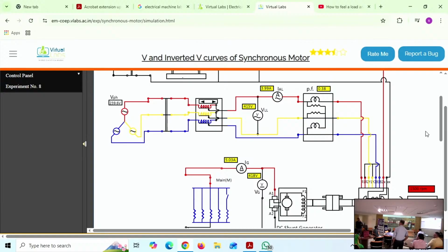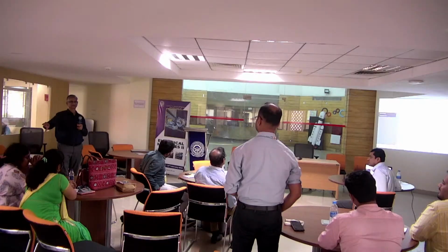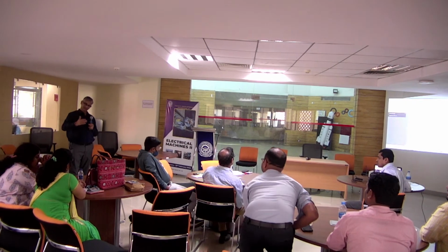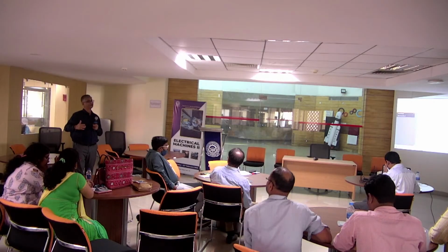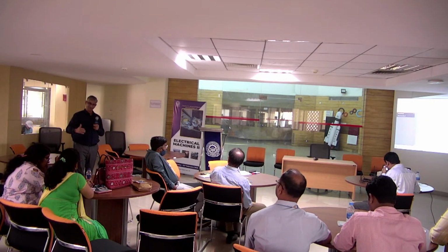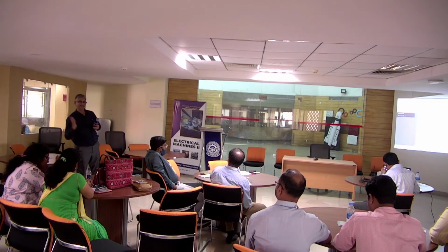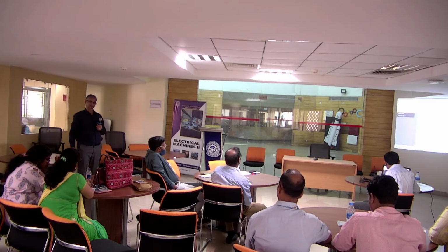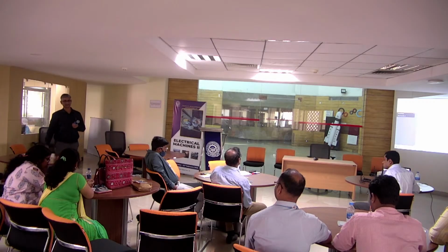But if you are really doing it, you will see each part. You are keeping the load constant, no? You have given the load constant. Only you are varying the excitation, the DC excitation. How do you vary it? Through the rheostat only. Understand? Up to this point it will come, then the wattmeter will read negative after this. So you keep it here, connect it, then you vary here, then it will go to the other side. So you have to take extra precaution.